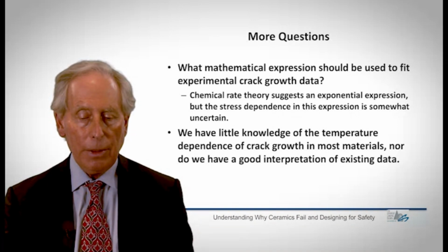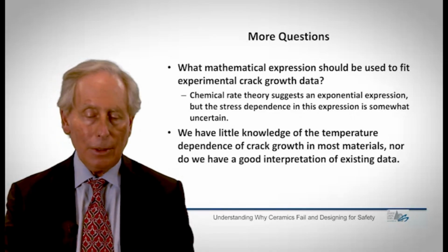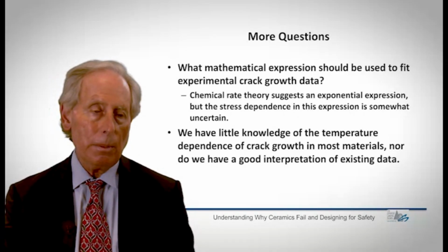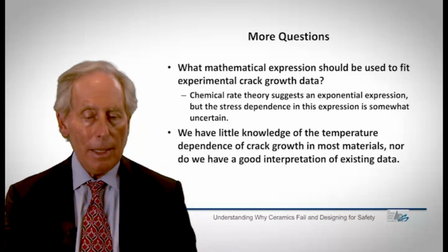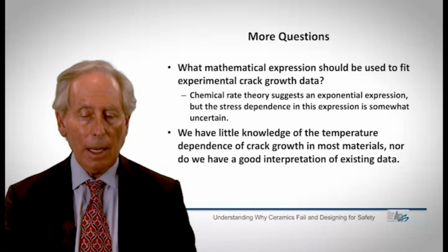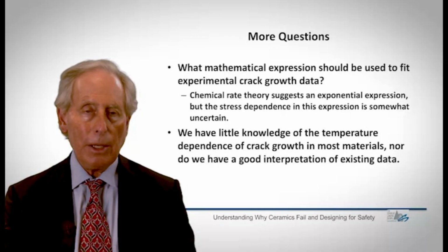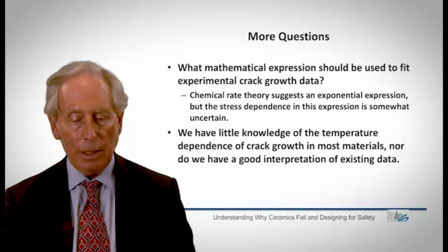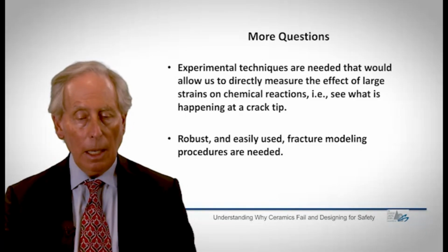We don't even have a method by which to approach that problem. We don't know the primary factors governing the slope and position of crack velocity stress intensity curves. We don't know the actual stress at a crack tip. We presume to know it from the elastic properties of the material, but it may not be so. And we use fracture mechanics, and I've encouraged you to use it, but it really may not give the right picture of what's going on at an actual crack tip, and differences in behavior may be due to different crack tip structures. These are kind of controversial topics.